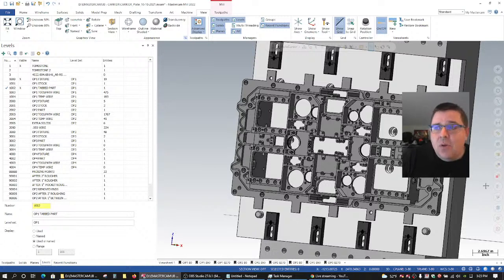So for example, if we're not cutting in any of those holes at this stage because we're just roughing all the material off the back, we're going to flip it over, we're going to rough all the material off side 2, just to let the whole thing relax before we go to start doing some more advanced finishing on the part, then it would benefit us to remove some of these features.